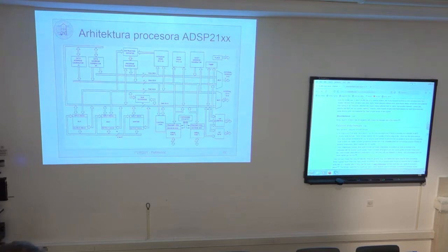The arguments of these execution units are located in dedicated input registers. So this ALU has X and Y registers, for the X and Y branch. At the entrance of this unit, we have these dedicated ALU registers. The same is for the MAC unit, and the same for the shifter unit. Data finally is fetched or stored from RAM, from data space.